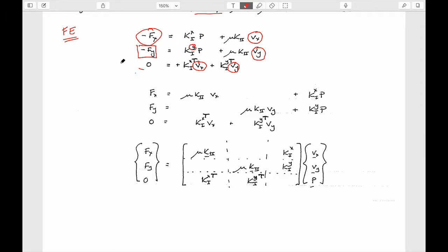In the same thing that we did when we first derived the conductance relationship for finite elements for a one-dimensional porous media flow node, we split this now into nodal variables. So these now would be nodal variables of pressure, velocity in x and velocity in y. So we can think of these as being vectors that operate on matrices, and these would also be vectors as well.